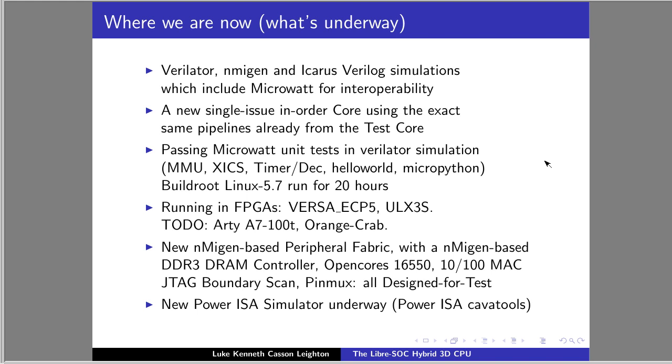Pin A5 must map to I2C, GPIO5, UART transmit, and SPI MOSI lines, and it would generate the code for that, the HDL for that. But it also generated the interrupt lines and connected all of those up automatically, and so on and so forth.